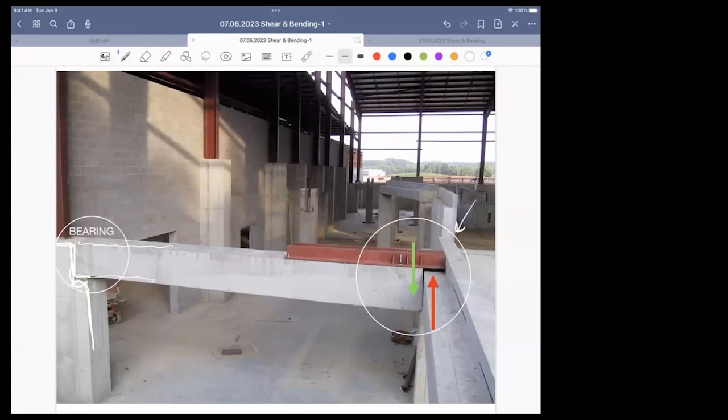So bring in somebody who's very, very strong in shear because the beam wants to go down, and the reaction is this angle here, transferring shear and preventing the beam from going down. So this pair of angles have to be extremely thick and sturdy.